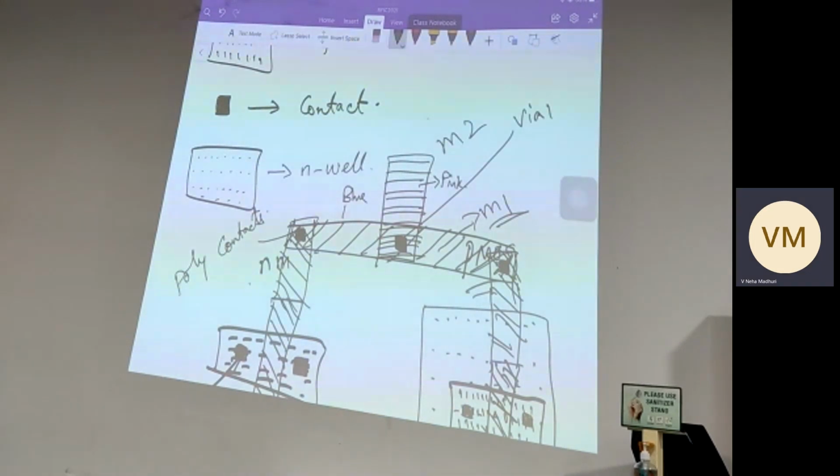How will they know if all are equal? You are not differentiating. They are all holes, holes, holes. How will they know which hole is for which layer? Therefore, we have to differentiate between the holes. This hole is for the ground floor. This hole is for the first floor. This hole is for connecting the second floor and third floor. Clear?